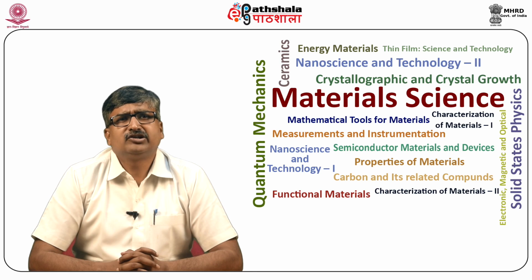Another advantage is the larger bulk excitonic Bohr radius, 24.3 nanometer versus 4.7 nanometer, for more prominent quantum confinement effect even at larger material dimension, and compatibility with high-k dielectrics, enabling integration into current semiconductor processing technology.